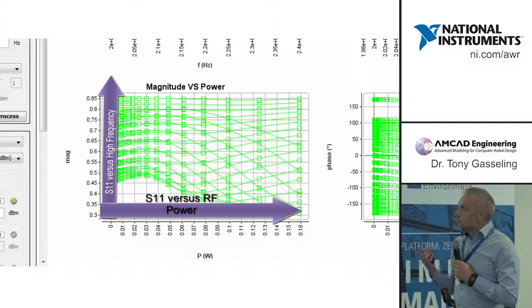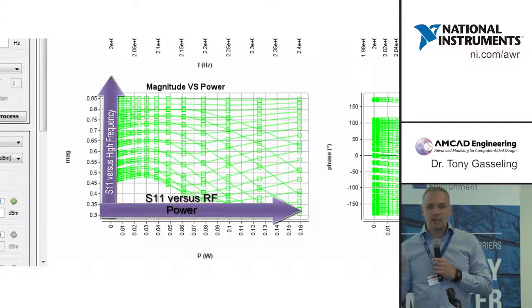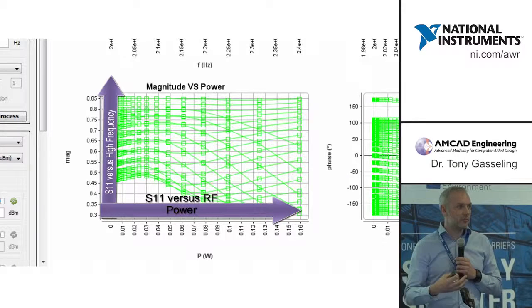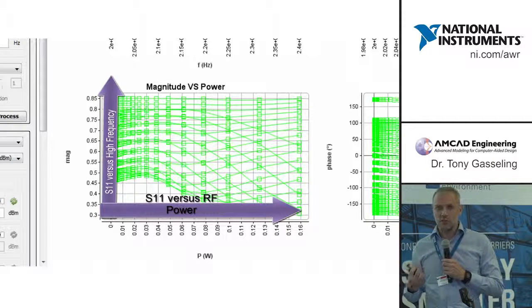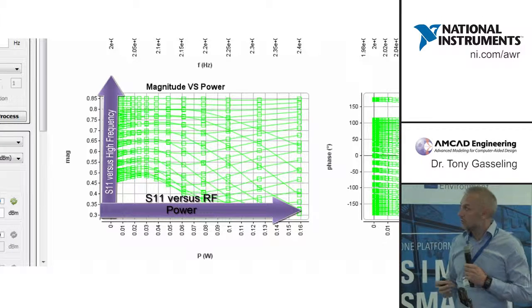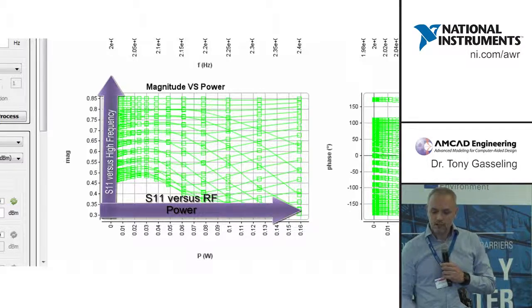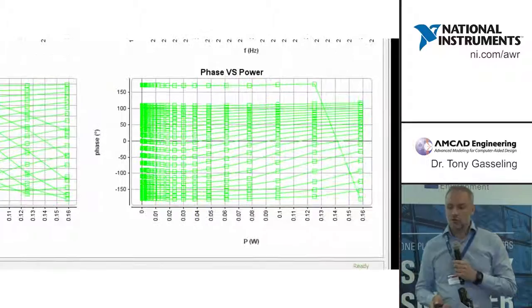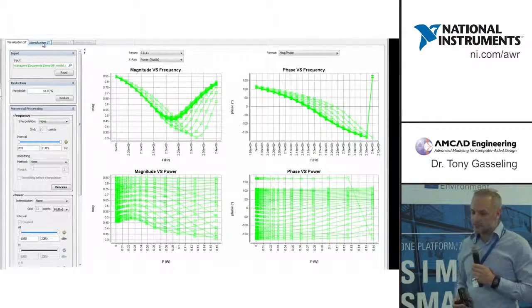It can be useful to get a feel for how the data behaves before the model extraction, because if you have noisy data, it will be hard to use the model in a simulator, especially if you have hundreds of models working together. So we need smooth variations. We can observe the magnitude, but we can also see the phase for these model kernels.